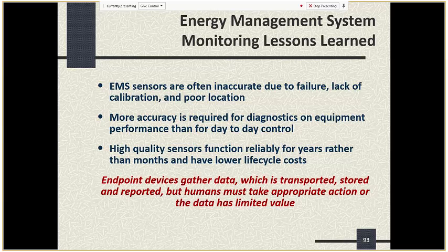It was a little bit perplexing in terms of why the space temperature was just going out of bounds and we were not able to maintain it. The human interaction, where the brain trust is all of our systems or our logics, was indicating we had a problem. But the real solution is that the space sensor was located on a wall that was in the afternoon sunshine.